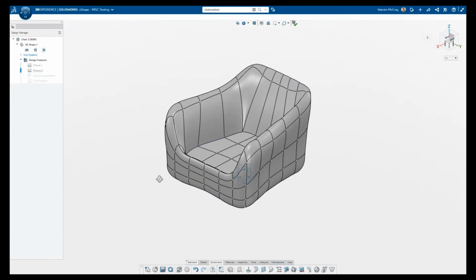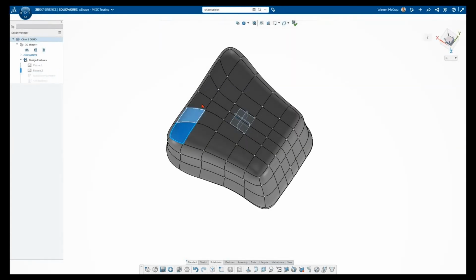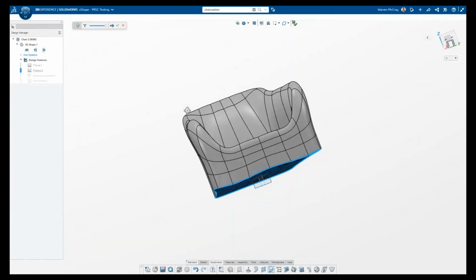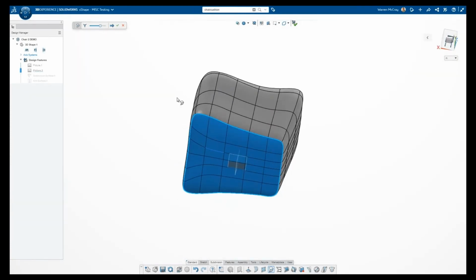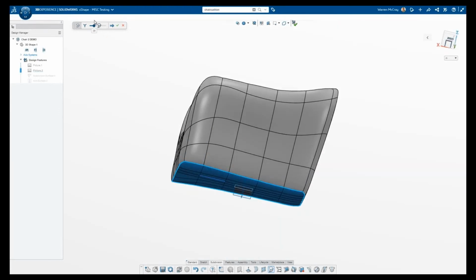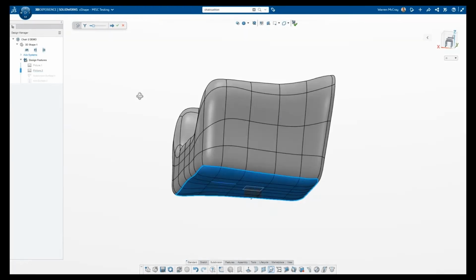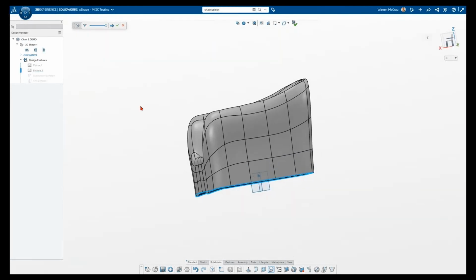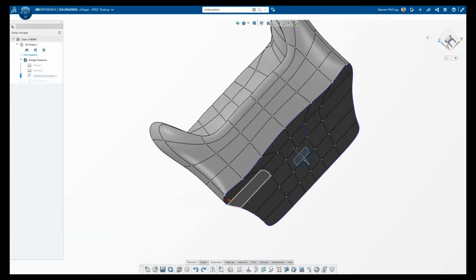In this case, I'm control selecting all these faces real fast here. And I'm going to go ahead and crease the edges, pull those edges down and flatten out the surface. And actually sometimes depending on how you select that slider there, it can be a flat enough surface where you can actually make it a sketching plane in SOLIDWORKS. So in this case, it's flattened, but the vertices aren't straight. So what I want to do is select the vertices and straighten them out using the line tool.